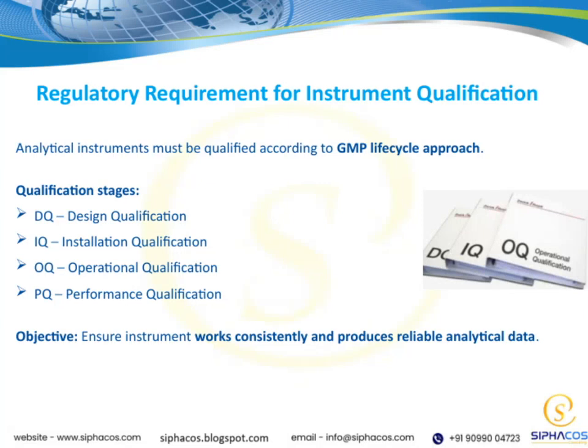Let's talk about the regulatory requirements for instrument qualification. In a GMP environment, it's essential that all analytical instruments are qualified using a life cycle approach. This ensures they perform consistently and reliably throughout their use. The qualification process is broken down into several key stages. First, there's design qualification, or DQ, where we verify that the instrument design meets our intended use and requirements. Then, we move on to installation qualification, or IQ, which confirms that the instrument has been installed correctly and is